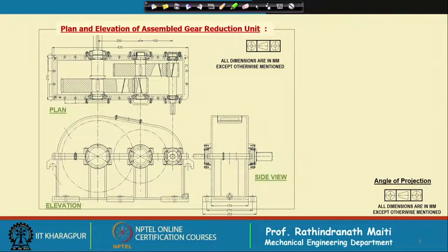It is always better if you can present something in 1:1 scale. And we have followed third angle projection. You know what is third angle projection. If you look into this, the icon is given here. So, we have followed, if this is one view, the top view, the side view from this side will be this one. We are not following there, so we can put a cross over there.